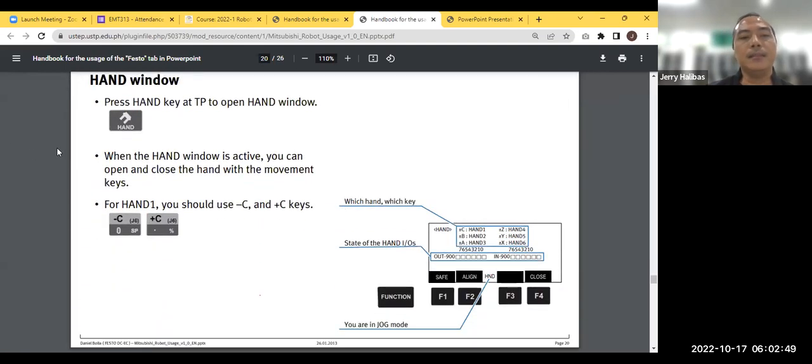Okay, for the hand, the servo is not needed. So you can release the dead man switch. You can click the hand as long as the enable button at the back is turned on. Then when you press C minus, it creeps, and C plus releases. But anyway, try to look at the response as you press the button C plus or C minus.